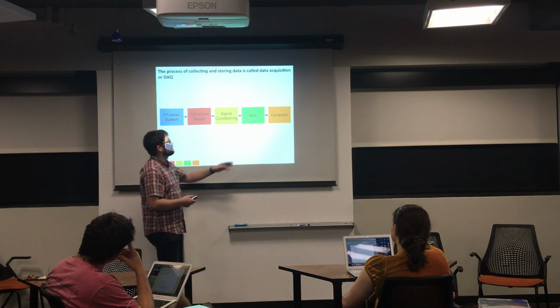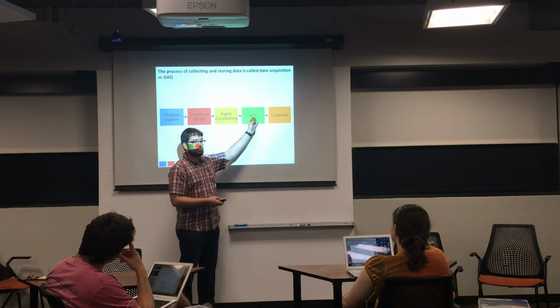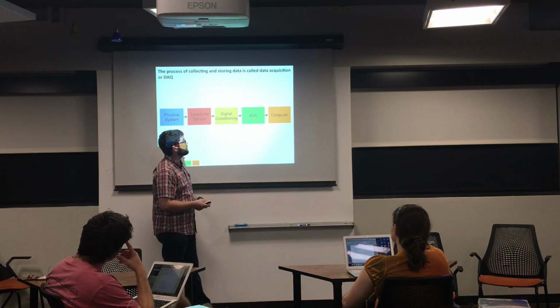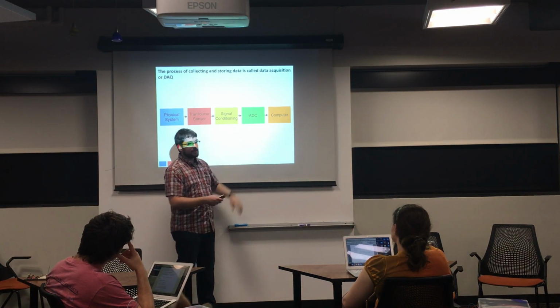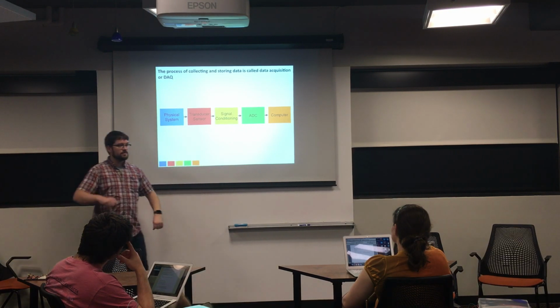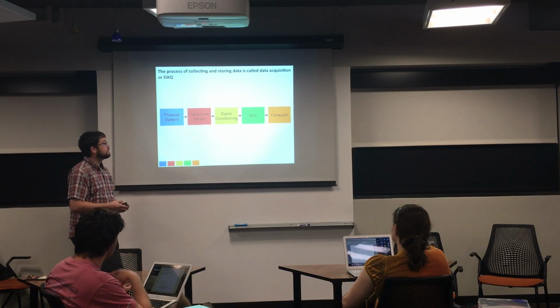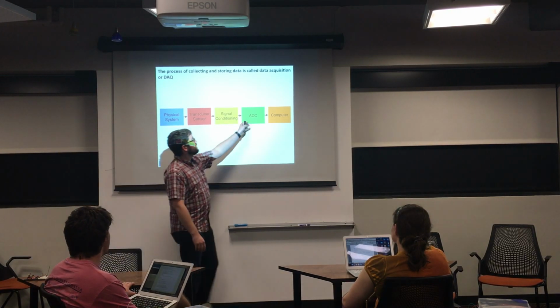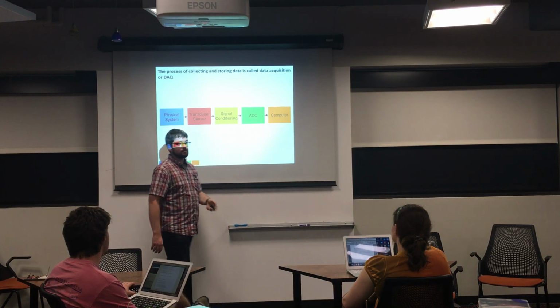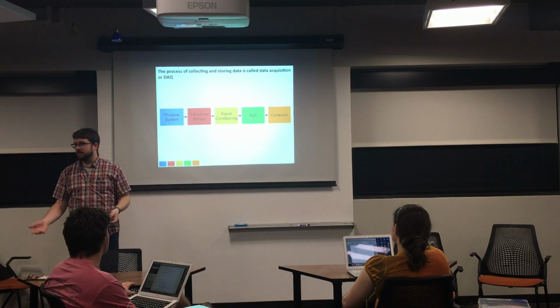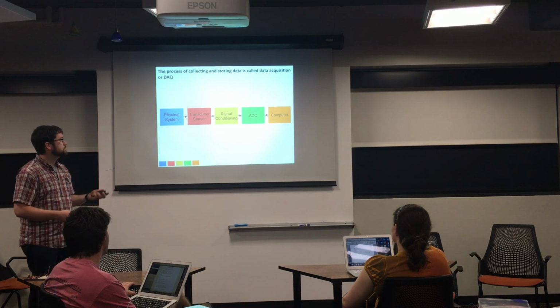And then it has to go through, generally, an analog to digital converter, assuming it's an analog transducer, which takes some analog voltage, any voltage, let's say between 0 and 5 volts, and turns it into a digital number that your Arduino or your computer can store and can understand. And then the value from the ADC gets passed to the computer, where you do whatever you're going to do with it: real-time analysis, control, storage, whatever.